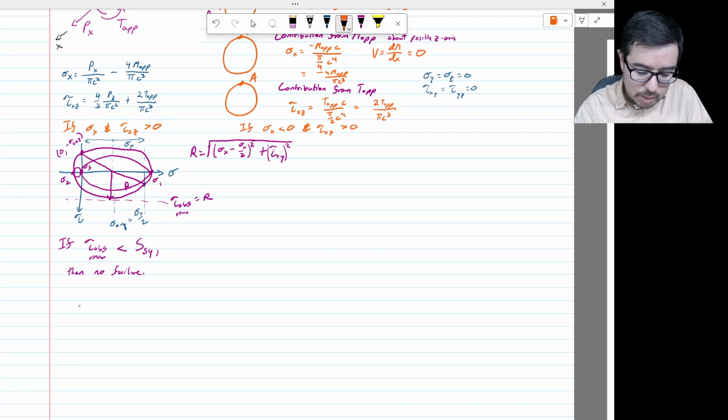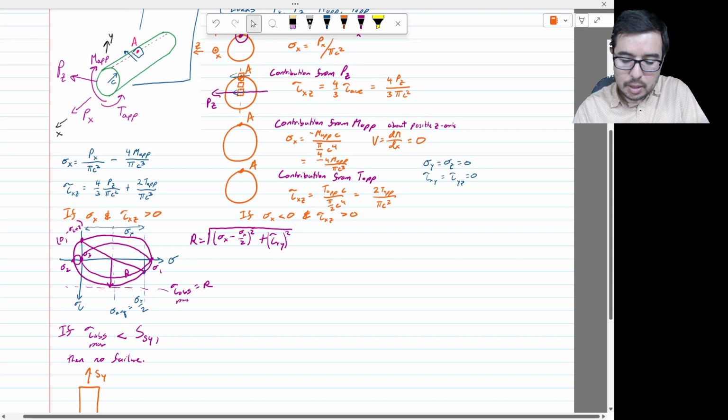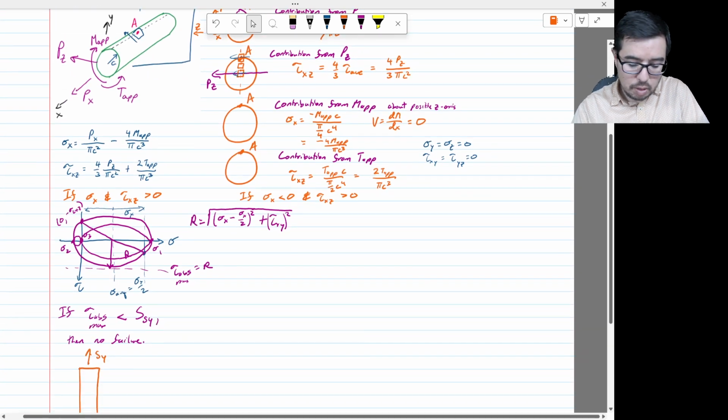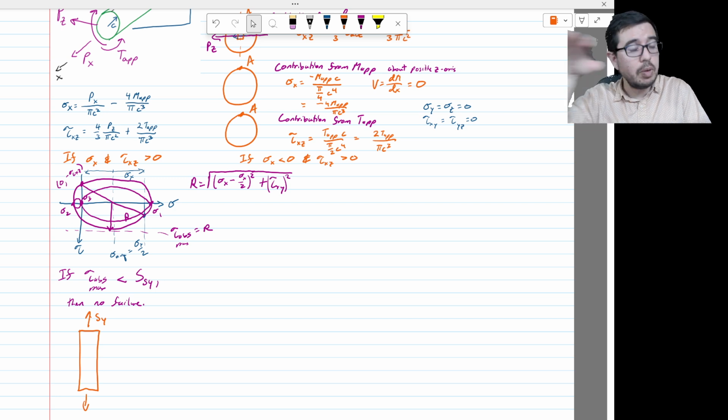The most famous method of loading and material testing is the tensile test, right? And this is loaded to the yield strength, and they did give us the yield strength, right? It's loaded to the yield strength because that's when we're going to have yielding. That's when we say we have failure. Okay, and if we're using a linear elastic, perfectly plastic model, that's where it flatlines, right?